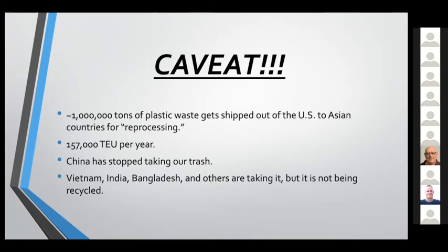We took carbon powder, we put it into a cylinder that was made of a very basic kind of plastic. We pressed it in, and then we took leads and we pressed those in on either end, and we sealed the unit so that the pieces wouldn't come apart. And then we put them into big containers and we bathe them in liquid wax and we cook them for days.